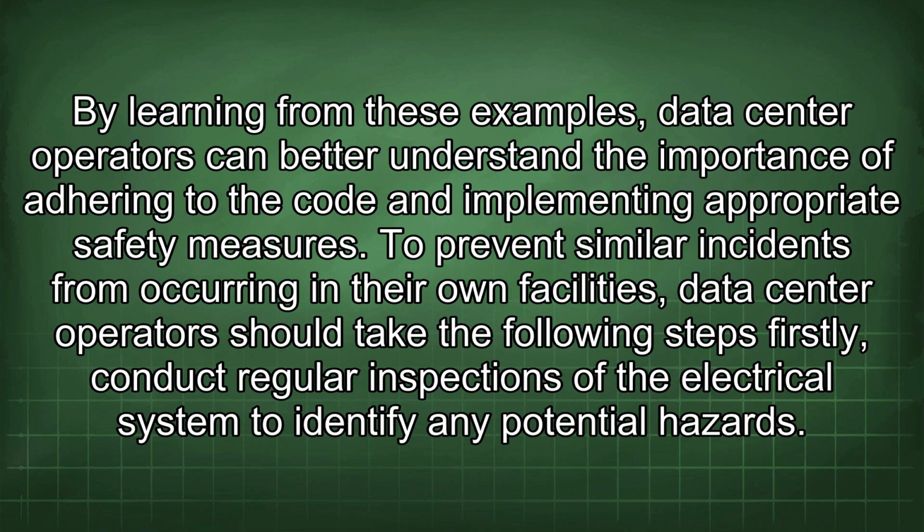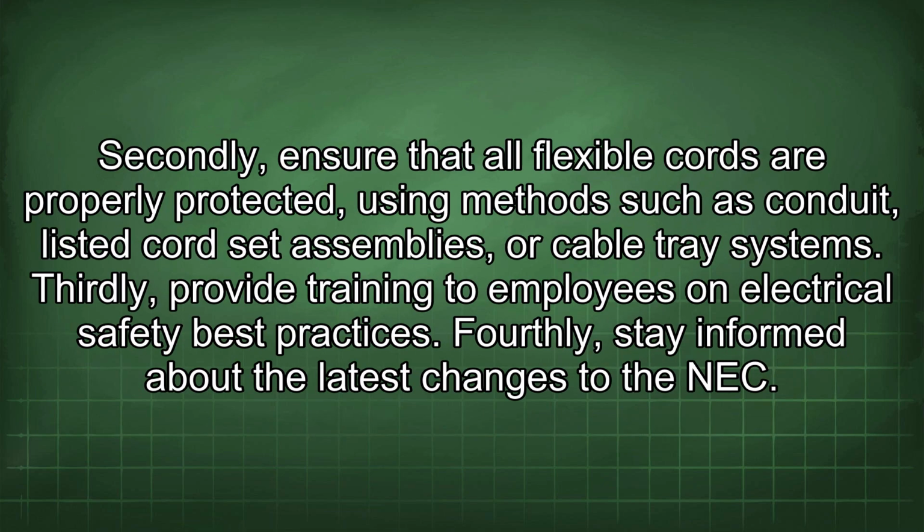To prevent similar incidents from occurring in their own facilities, data center operators should take the following steps. Firstly, conduct regular inspections of the electrical system to identify any potential hazards. Secondly, ensure that all flexible cords are properly protected using methods such as conduit, listed cord set assemblies, or cable tray systems.